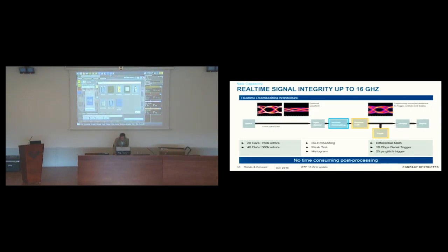And also I have this adapter here, from precision BNC to SMA. This precision BNC is the connector that is the input connector of the oscilloscope channel. So as you can see, this tab here is real-time de-embedding. If I don't apply this real-time de-embedding, I can enable de-embedding by software. The advantage of doing it by software is that it's a little more accurate, but it's much slower, and I cannot trigger on this corrected signal.